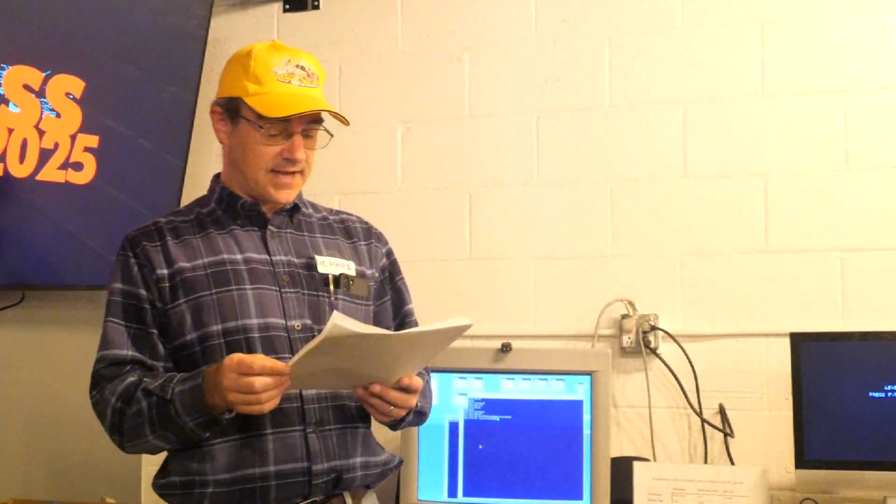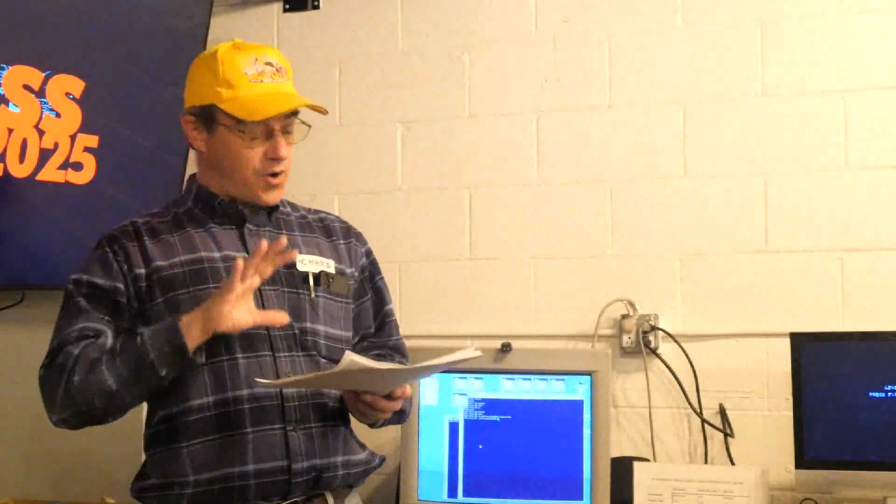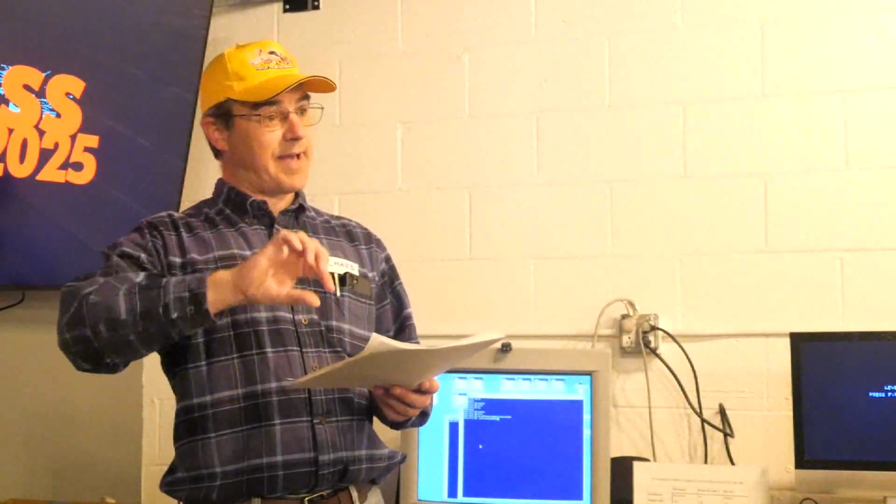Another big one that really opened up the market on the PC side was the Monster 3D, which used the 3DFX Voodoo chip. The 3DFX Voodoo chip couldn't do 2D. It didn't have a frame buffer. It could only do 3D, and so you had to have a pass-through and have another video card that was your main video card, and then that 3D card, the Voodoo, was just for the 3D graphics.